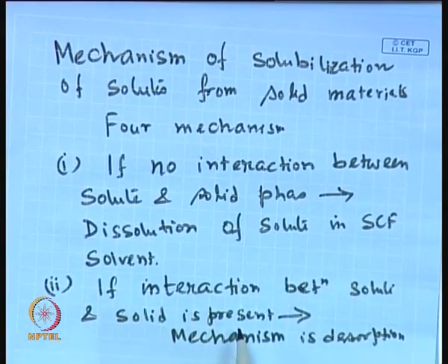Similarly, in the case where there is an interaction between the solutes and solid matrix, that means the solutes are attached to the solid matrix by weak van der Waals forces or chemical forces. Okay. Now, if you add the supercritical fluid, these solutes will be coming out of the solid matrix, and the mechanism is exactly like desorption. Okay. And desorption will be dictated by the desorption equilibrium isotherm.